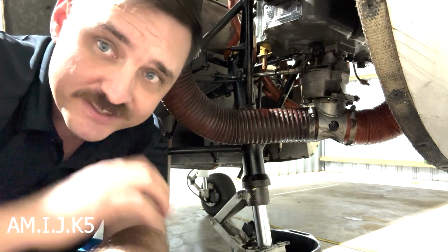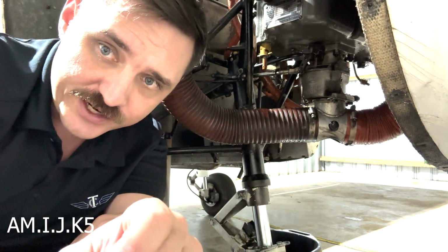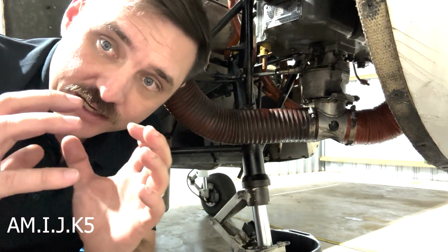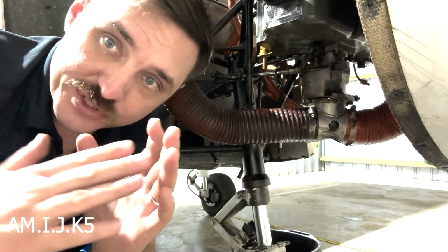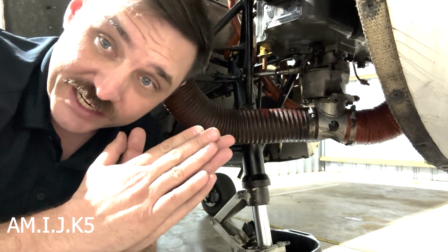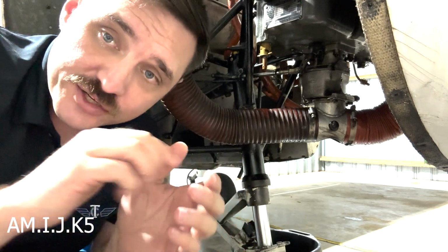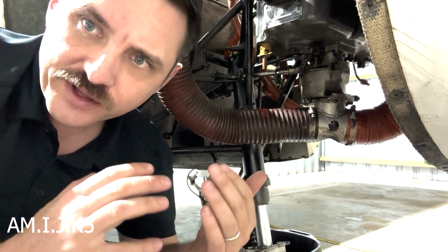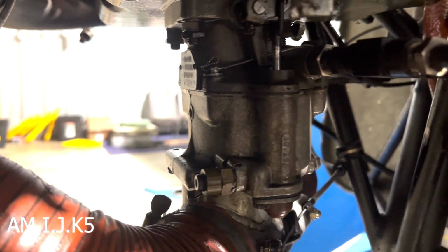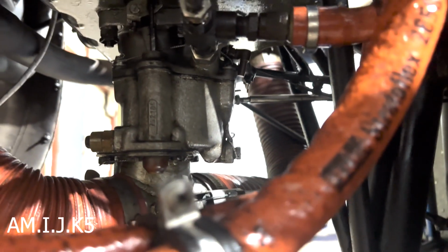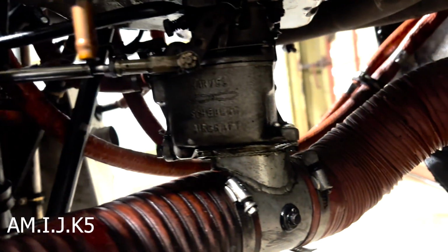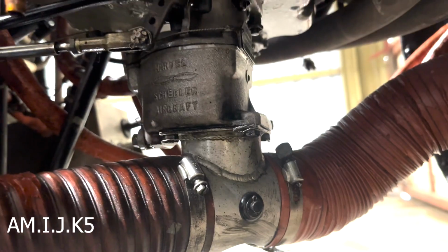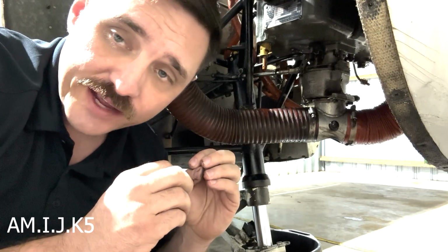All right, so one of the classic examples of a Venturi tube use is a carburetor. What the carburetor does is it takes air and puts the air through a Venturi tube to increase the speed and lower the pressure, so that fuel can be injected into it. So here we have a Cherokee 140. We're going to go over the process. Air enters in here, goes up into the carburetor, gets squeezed into the Venturi tube, increasing its speed and lowering the air pressure.